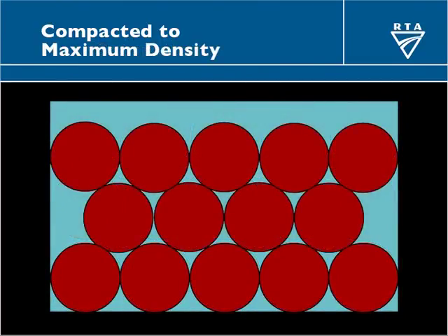Now, we can also imagine this with all the air gone, so it's now saturated. Now at that point, if we want to make it denser, there's no more air to squeeze out. So we can, but it comes with the effect of squeezing some of the water out. Now in this case we have soil at its most dense condition, and what we see above it is the water that has to be squeezed out in order to achieve that compaction.